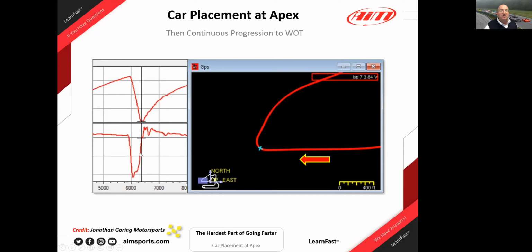In the bottom, we have GPS longitudinal G, or perhaps the real G, the accelerometer G in red. And then you can sit there and see the attack of the brake aggression, how quickly this deceleration rate rises. We can see that the deceleration is front loaded. It happens early in the braking zone. We're going to come back to this.